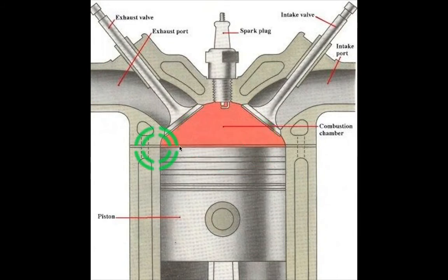When the piston is at this, your TDC, you see these two lines, this is your top dead center, right? This is your piston, this is your piston pin, this is your connecting rod, this is your cylinder, and if you have sleeves, they're gonna be here. The cylinder liner is also called a sleeve. And this is your head. Above this, your top dead center is almost kissing the head. Your head has two ports, the intake port and the exhaust port, and there are two gates on that, which you can call valves, right?